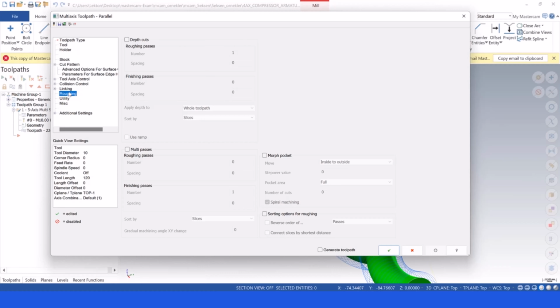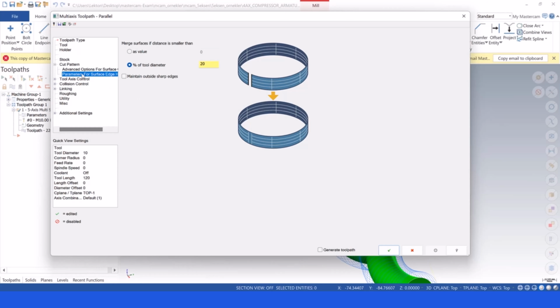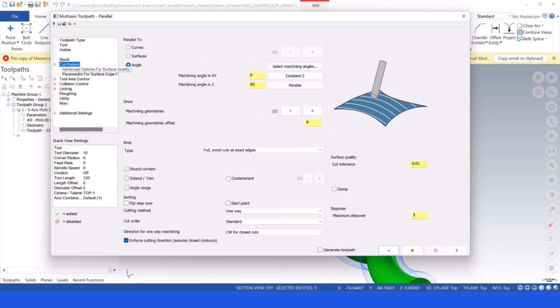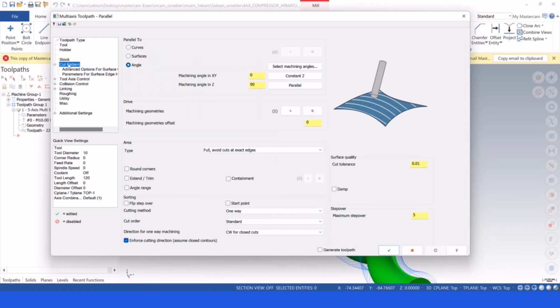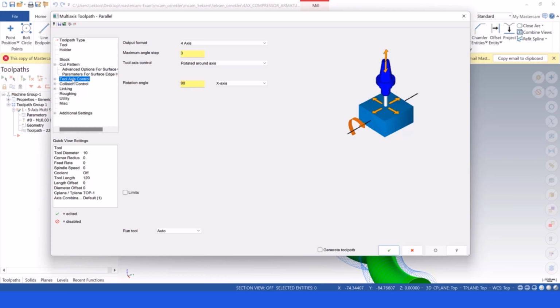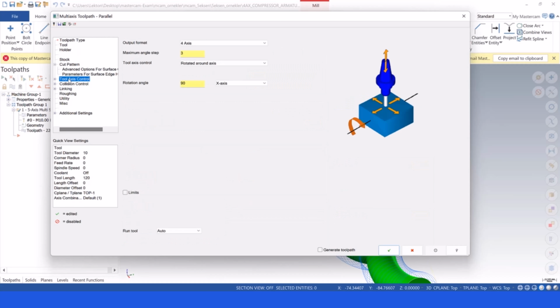And what can I say about here? When we turn to cut button, as a summary, I can say that toolpath type, when you select your toolpath type, all that stuff is organized. After that process you need to focus on the cut button and tool axis control. In the cut button process, we decided our cutting parameters, but when we turn to tool axis control, we need to organize our tool axis because we have actually finite possibility.